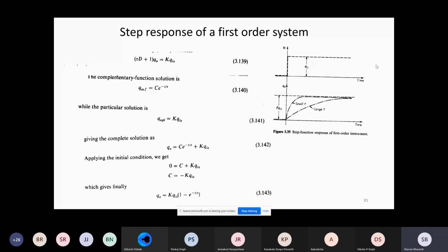Another way of doing it, which is very complicated, is to convolve the time domain transfer function of the instrument with the time domain input, so that you get the time domain output. But that is quite tedious and nobody does it. Now the input of any device may not be a standard one.